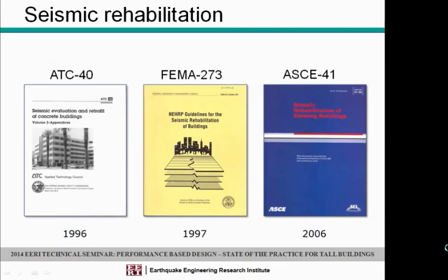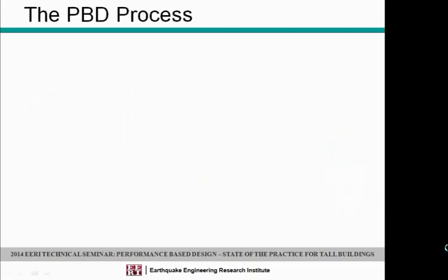And these were really the first true performance-based design standard-like documents that were available to the industry. Today, they're both embodied in ASCE 41, the Seismic Rehabilitation Standard. And this really forms the basis for performance-based engineering practice today. And much of what you hear about today, whether the designs are conducted per the PEER documents or the LA Tall Buildings Council document, really the technology that they're using is the ASCE 41 technology, developed in the mid-1990s for the ATC 33 and ATC 40 projects.